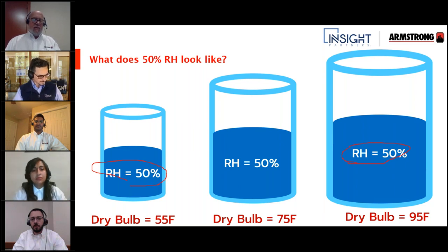And you can get them in anywhere from 1%, 3%, 5%, 10% accuracy, and it depends on what you're using it for as to what accuracy level. So if I'm trying to control space humidity in my house, a 5% accuracy sensor is just fine. If I'm trying to control relative humidity in a chip manufacturing plant or in a hospital OR, I may want a 1% or a 3% accuracy sensor, but understand the price associated with those goes up. The sensor I have in my house to control my humidifier is about $100. If I put a 1% accuracy sensor in, I could be up over $1,000.